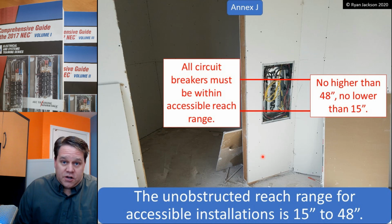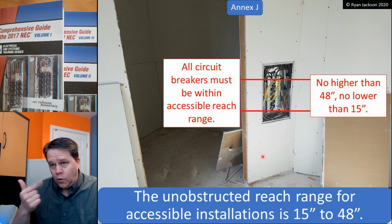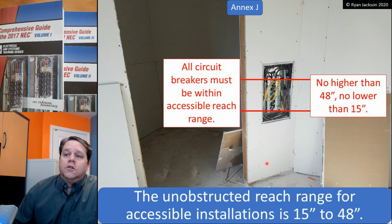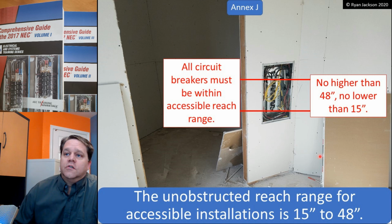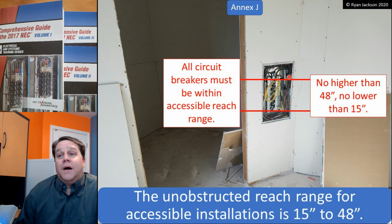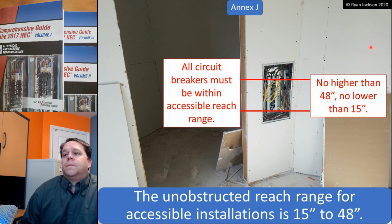Another example, we talked about apartments. If I'm doing apartments and they're accessible, or Type A, or Type B, maximum and minimum reach range has to be accommodated. That would include receptacles, light switches, thermostats. That would even include circuit breakers. And in fact, it specifically says that it includes circuit breakers. So here we've got a panel board where the highest circuit breaker is 48 inches. That is a requirement. It seems very low, and perhaps it is. But that is the requirement. No lower than 15, no higher than 48.